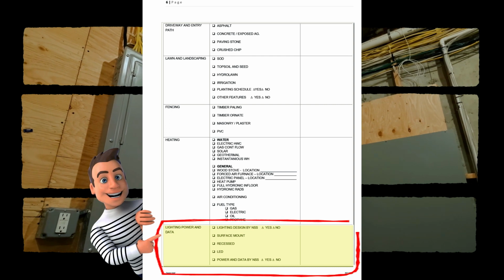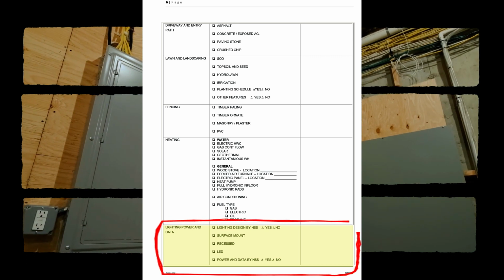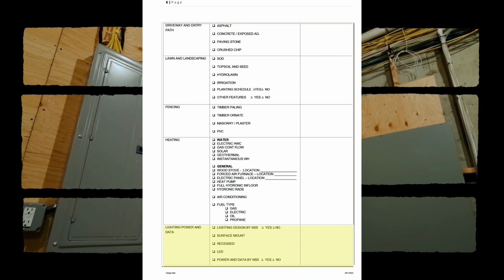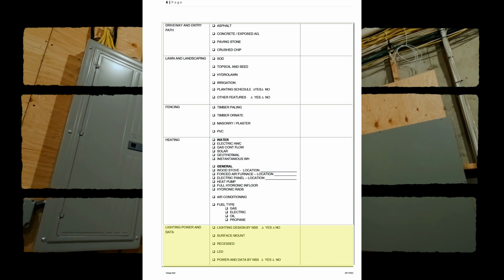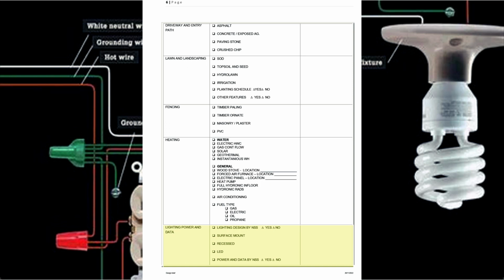The next section will cover the design of the electrical and lighting installations of the house. If you choose to provide these services to your clients, as many jurisdictions do not require electrical system designs and drawings as part of the building permit process, you should note any preferences and specifications in this section. The electrical design will be further refined once a floor plan has been approved by the client in later stages of the design process. Noting the size of the electrical service required may be warranted at this stage and cross-referenced with a subsequent section on site services.